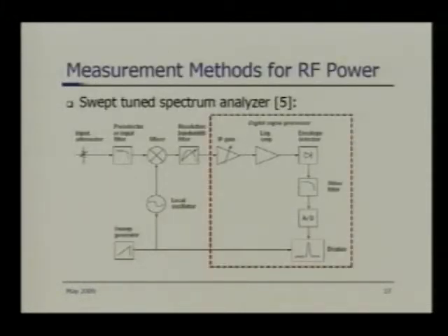Now, from this point on, what I am going to consider is, to measure a specification on the RF output, what are the different approaches that exist that you're going to use on the bench as well as in the automated test environment. There are several approaches for measuring RF output power. Some are frequency sensitive, some are broadband. I'm going to go through a few of them.